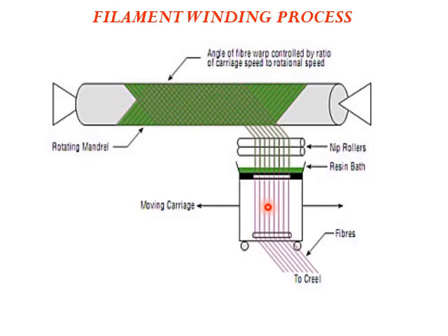Now what will happen here? First the fibers are taken out of the creel and made to pass through rollers, where they are aligned in the proper direction. Then they are made to pass through a resin bath. Once they are taken out of the rollers, they are impregnated, or in general terms, dipped into the resin bath. Once they come out of the resin bath, the resin is coated on them, so we call them impregnated fibers.